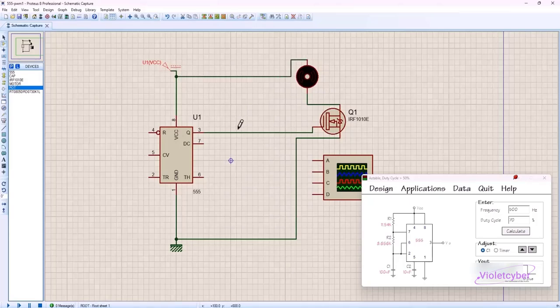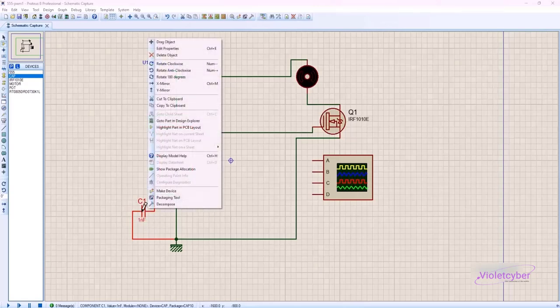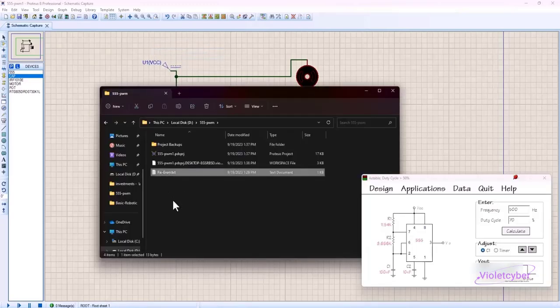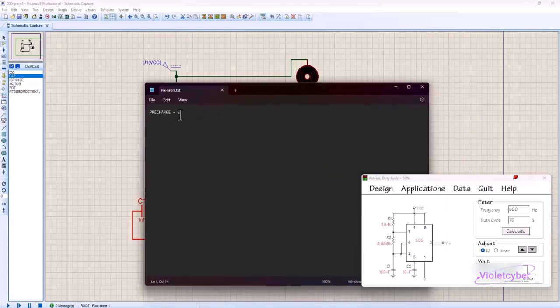Pin 8 is always the positive supply, just like we're saying here, which means it's a positive number. Then according to what is said here, we connect the 2 with the 6, so we do this, and then we connect the 2 with a 100 nanofarad capacitor to ground. And here we place the capacitor. I put it here before, and we'll connect one side to the ground. And we right-click, and we do this. When we were asked to convert to 100 nanofarads, we right-click in the edit section, and here we change 1 nanofarad to 100 nanofarads. And the code that I told you, you must copy that code, then come here in the properties, paste it like this, and click OK.